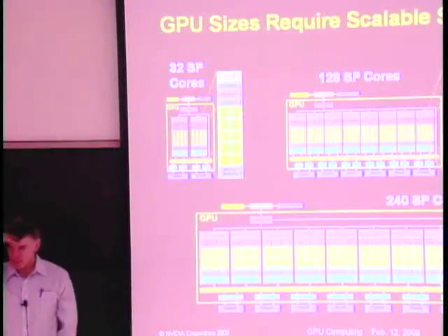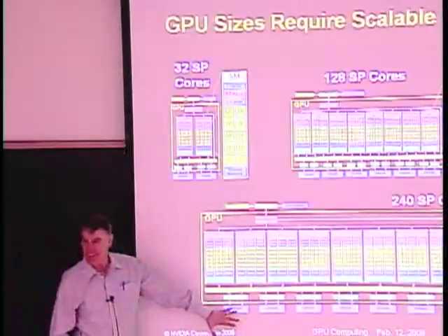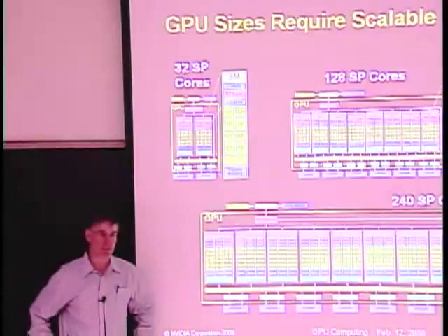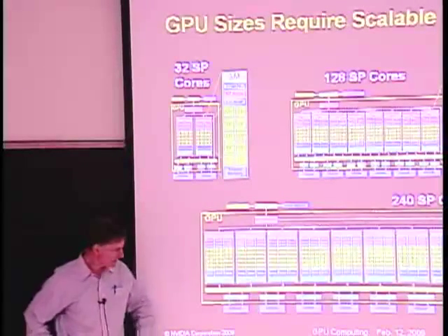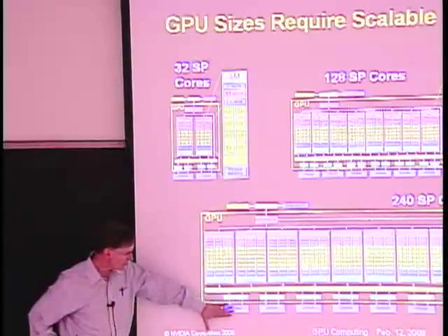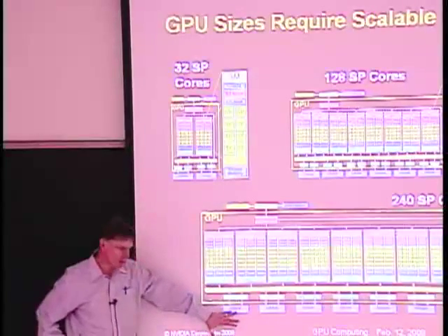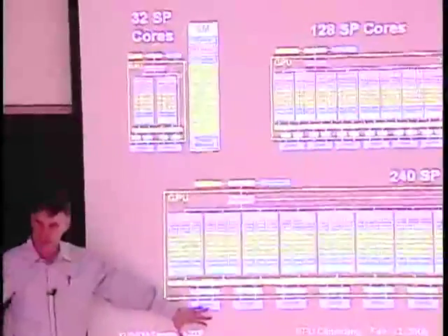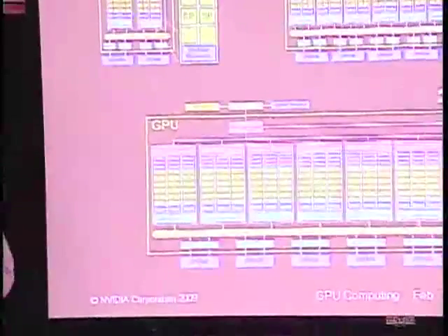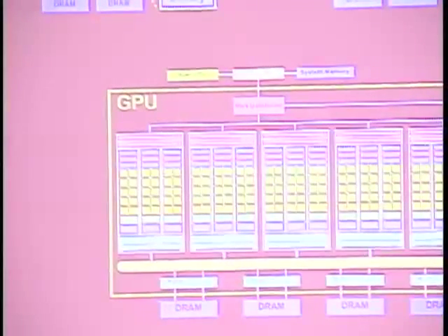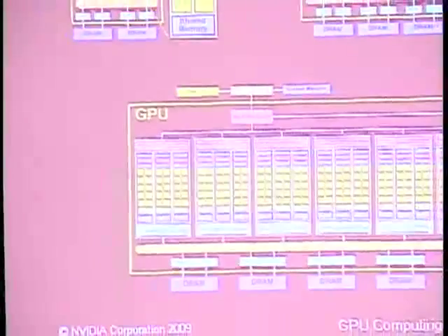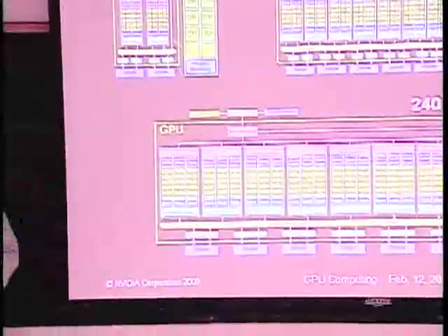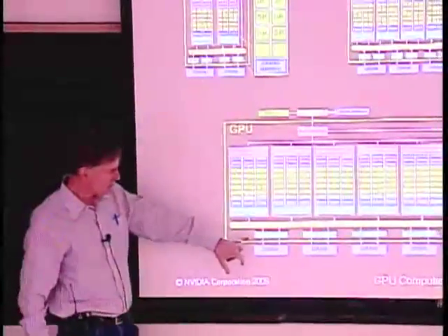Okay, number one. Number two, it's a pin count issue? It's where do you put your money, right? We spend a huge amount of money to buy the very fastest DRAMs. These are GDDR3 or GDDR5 DRAMs, and they're specifically designed to have high bandwidth and not that much capacity, whereas CPU DRAMs are typically designed for capacity first and speed second. So it's a physically different part.